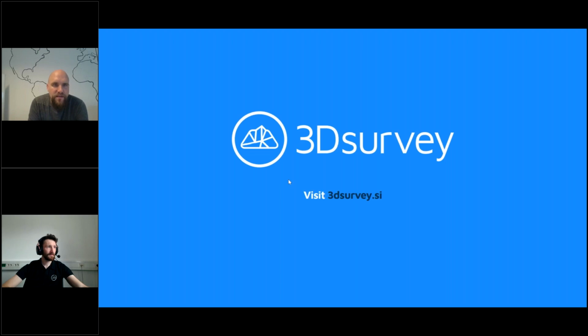There is a question from David. If we would not use video and just take photos with camera, would we expect better accuracies? You can also just use photos from camera, and if you set your camera up so that it stores the GPS location, and if you use the N-Trip client app, you will actually get RTK positions for your shots. I wouldn't say you will get better accuracy.